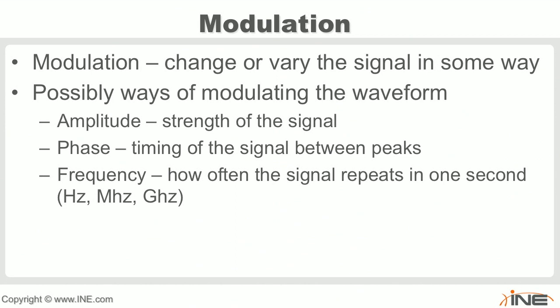We're going to talk about this quite a lot because one of the modulations we're going to use is called phase shift keying. It's a very popular one, at least has been in the past. Actually, it's pretty old, but the idea is that we change how the signal is. We start it, and then we stop it, and then we start it again, but instead of starting it right where we left off, we start it at a different place. We actually drew a little bit of this earlier on, but we will get back on the whiteboard and draw it again so you understand.